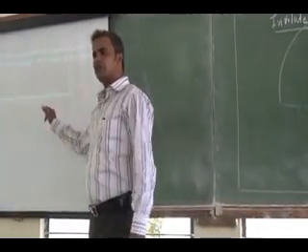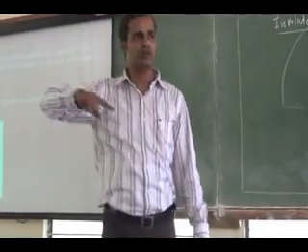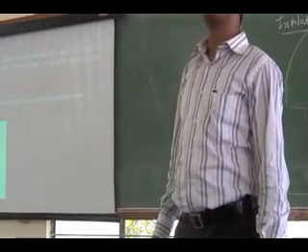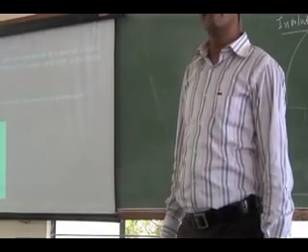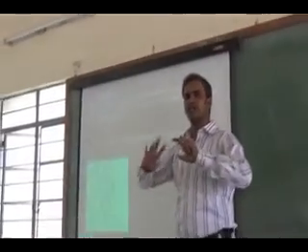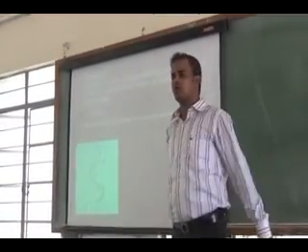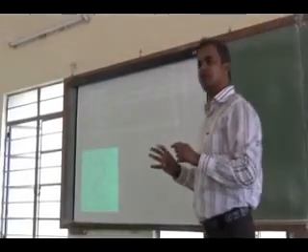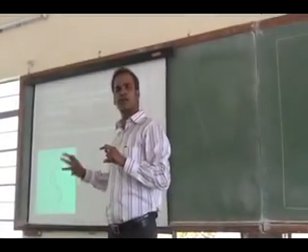Why is it essential that the gear teeth have an involute or cycloidal profile? Yes, that is to avoid slipping. Suppose you have any other profile while the transmission, the velocity transmission, has to occur smoothly to another shaft.